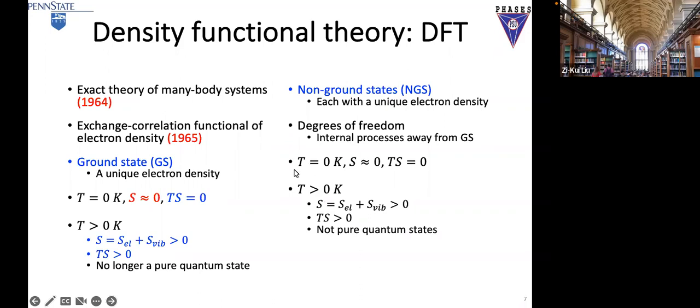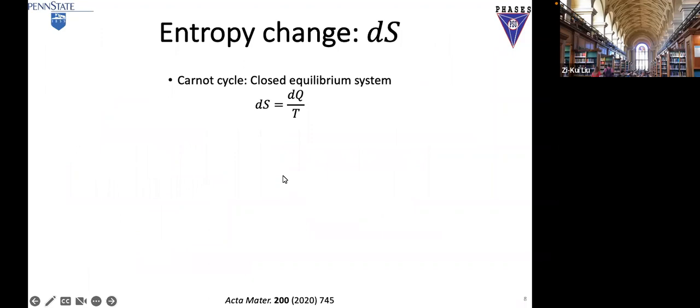Okay, now I'm going to just review what I was studying about entropy. If you take thermodynamics, the first equation you saw is dS equals dQ divided by T from a cycle. This was very important when we derived it: it is for a closed system at equilibrium, because all the processes we have are reversible. That's the first one, so it's for equilibrium. Now, if the system is at equilibrium but not closed, then you have to add another term, right? If the system is not closed, you have mass exchange. Each mass has entropy, so you have to add the partial entropy into the system.